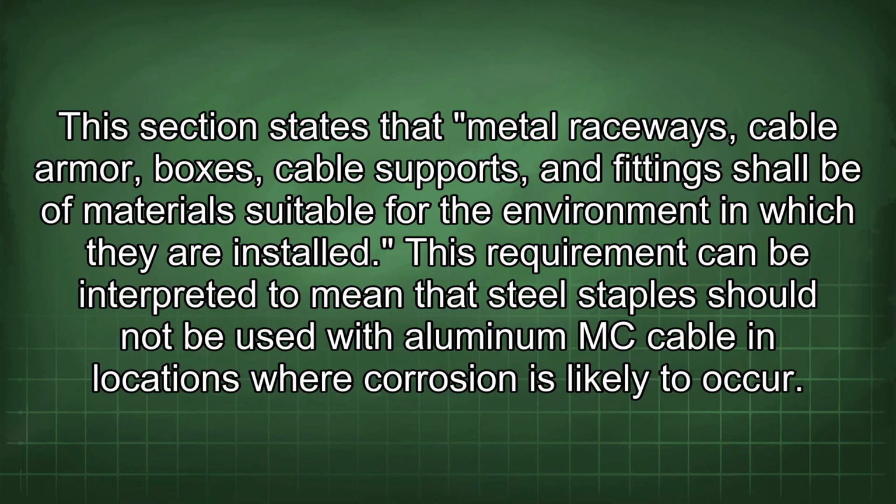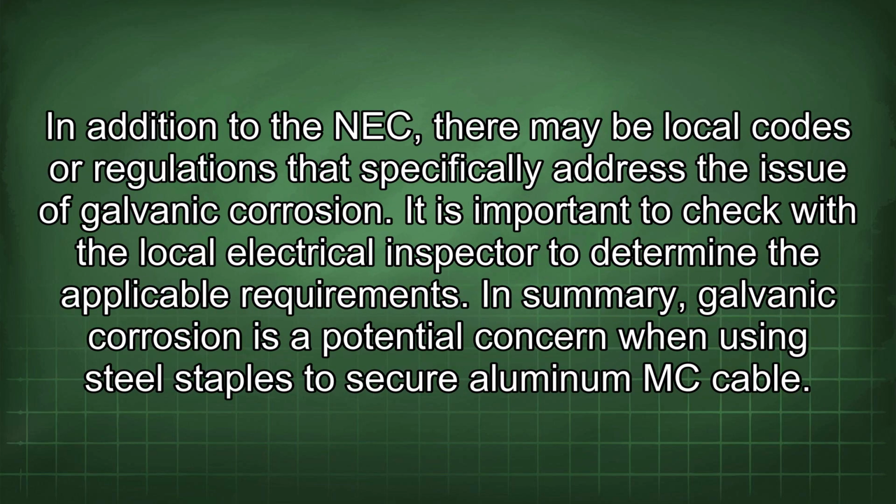This requirement can be interpreted to mean that steel staples should not be used with aluminum MC cable in locations where corrosion is likely to occur. In addition to the NEC, there may be local codes or regulations that specifically address the issue of galvanic corrosion. It is important to check with a local electrical inspector to determine the applicable requirements.